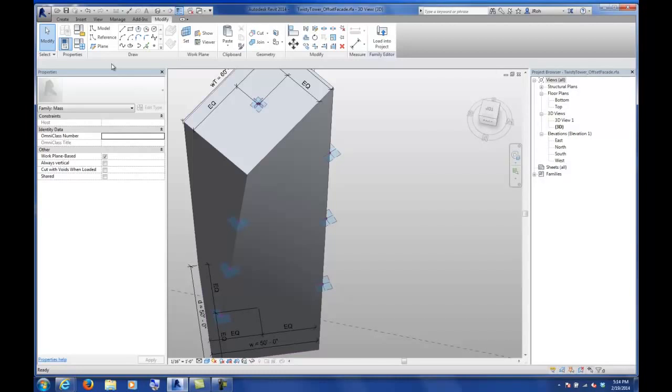Yeah, it's over the whole entire length of whatever the length of your line is, even if it's curving. So if I selected the non-normalized, that would be the proper parametric equation U value. Right. Okay, that helps me. So it doesn't matter what type of line it's on, it's always going to be 0.25 or whatever percentage along that path of the line, if it's the normalized.